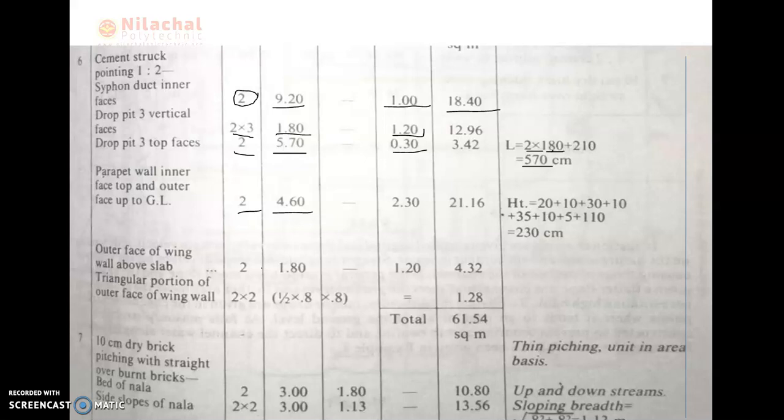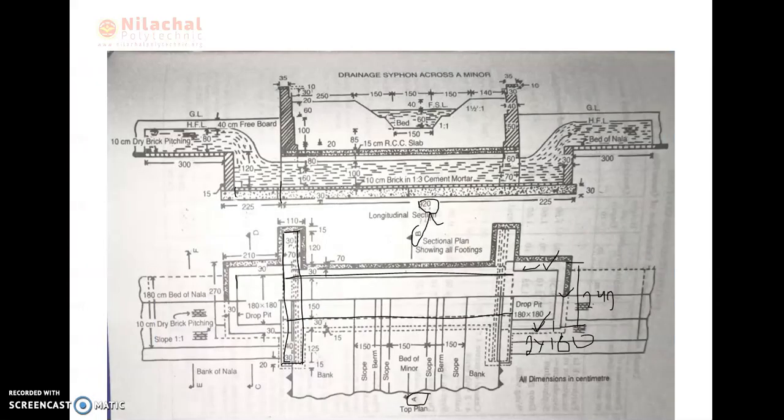So here actually the ground position is here. The ground, this point to this point distance we don't know. So from this point to this point we need to plaster here, right? Which is 60 plus 20 plus 30 plus 10, here offset also 10, here offset also 10, right?